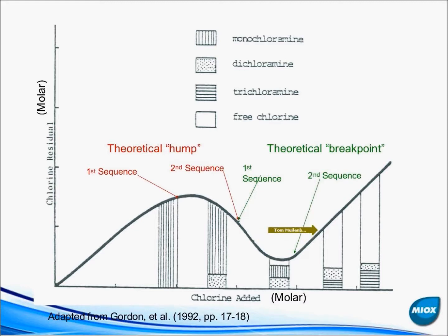And so the control of the system, if you're operating a system, and this is a challenge for you, you have to keep in mind that if you start dosing the system at, let's say, 1 part per million, you see 1 part per million, and you're still reading ammonia, it's because you haven't gotten past that break point yet. And this peak here is called the break point. So you haven't gotten past the break point, and you're not dosing enough. So what this usually means is an operator has to pretty well know what's going on with their system, what their ammonia concentrations typically look like seasonally, how much chlorine they have to add into the system, and so on.